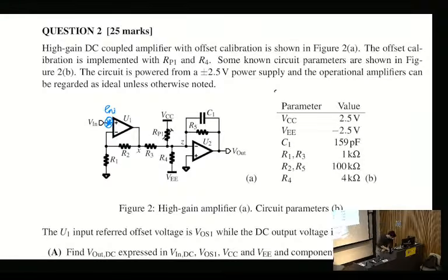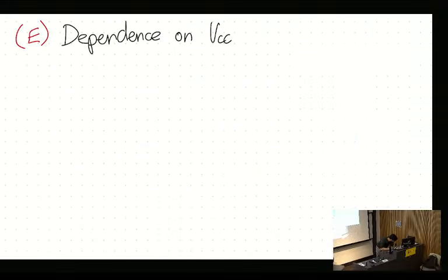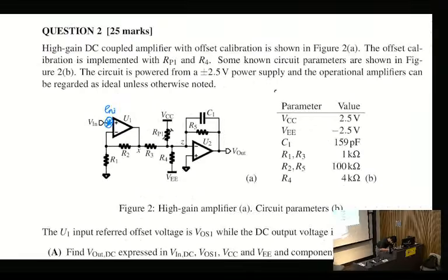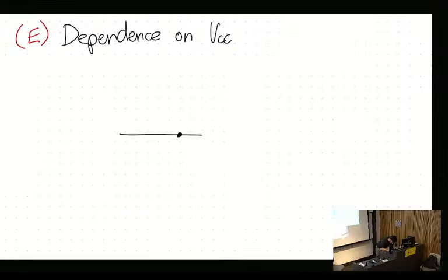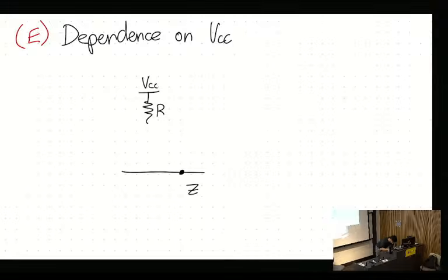So if I just draw it quickly, one thing we can do, if we have our output node here, so that's our output node, I think VZ, or just Z. So one thing we can do is R, and then we place a VCC, and then we place a diode, this to ground, and then we connect this as our reference voltage.